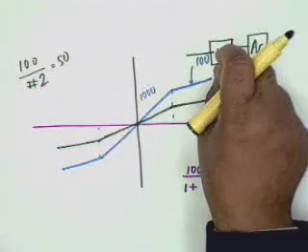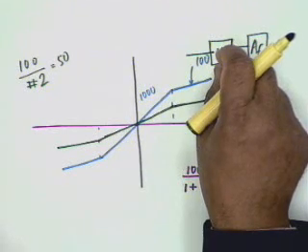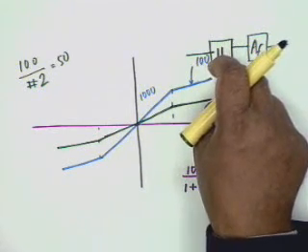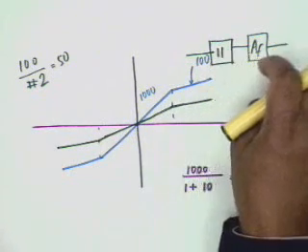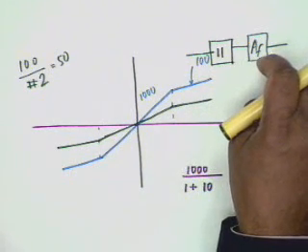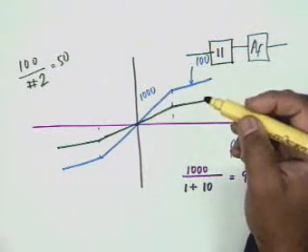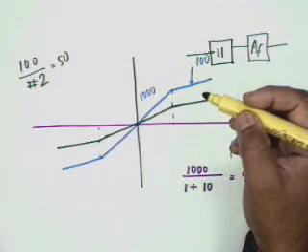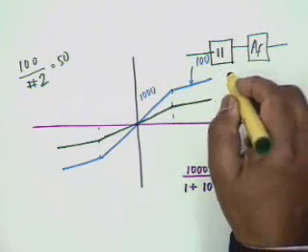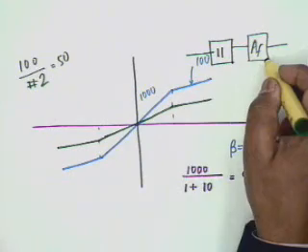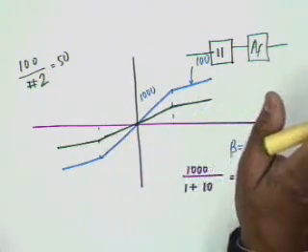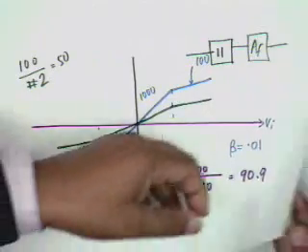Since the gain is small, the nonlinear distortion introduced by this pre-amplifier will be much less as compared to the feedback amplifier. Small gain, and therefore the excursion of voltage at the output will not go to cutoff or saturation, and therefore it is easy to design a low gain pre-amplifier to compensate for the reduction of gain in the feedback amplifier qualitatively. Now let us look at it quantitatively.